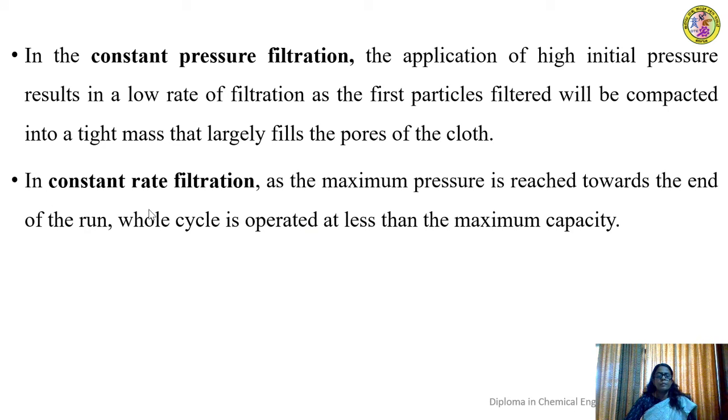Then what is the problem with constant rate filtration? In constant rate filtration, the maximum pressure will be reached only towards the end of the run. So the whole cycle of the filtration is operated at less than maximum capacity. So that is constant rate filtration.